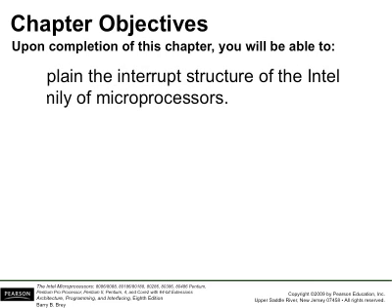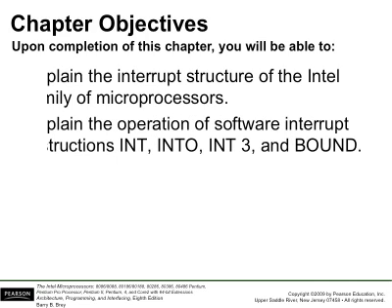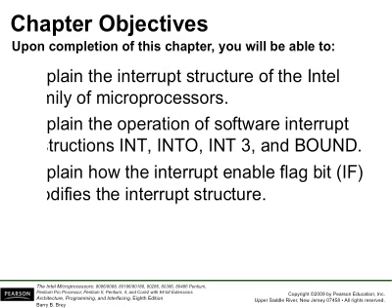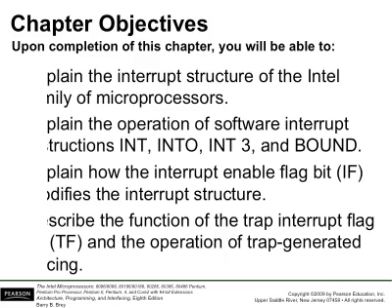This lecture is particularly relevant to Intel architecture. Other processors may have slightly different interrupt organization. We'll talk about several software interrupt instructions and also the interrupt bit that we use to modify the interrupt structure. Also, the trap interrupt flag we'll be talking about.